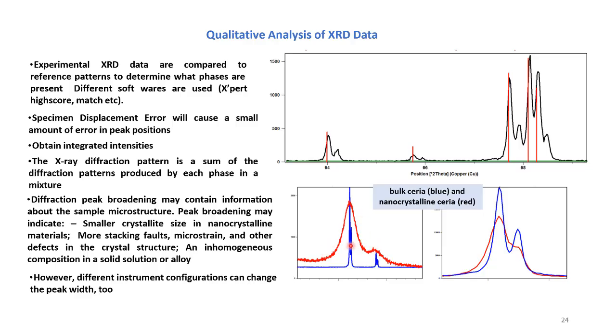However, in the bulk material, which is crystalline, we get a very sharp peak, as you can see here. This happens in XRD because in the nanocrystalline material we do not get very specific crystal information about the crystal lattice, so we get a very broad hump.